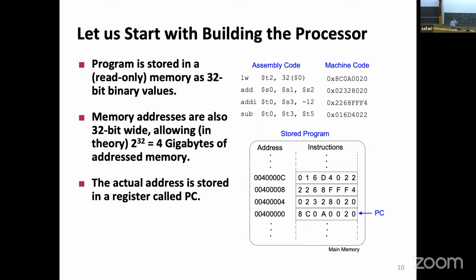Sorry, there was a question. Somewhere? Yes. Why don't we change up the order of the registers in the architecture? That's a very good question. I'll just repeat it. One of those multiplexers could go away if this one and this one had been swapped. Now, this was a decision of the architecture, made by the computer architects who were devising MIPS, and they were making certain compromises.